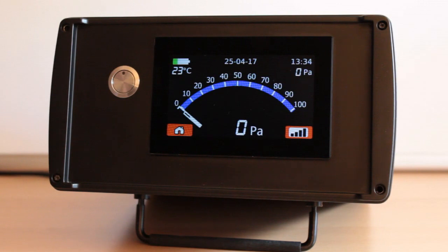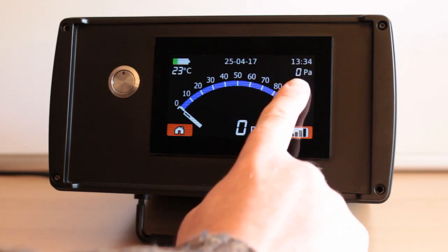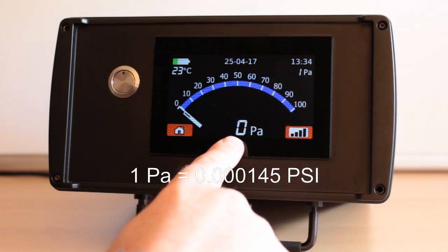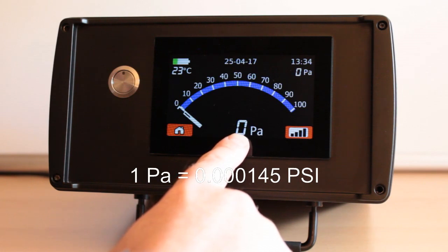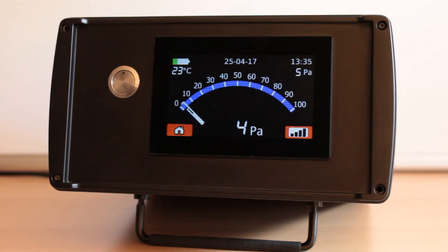Right, so I've got my pressure source plugged in, and it's running at absolute flat bus minimum. What you might notice is that this will flicker around somewhat because this is a live readout, whereas this is damped down somewhat. It is an average over the last 4 seconds, so it's a little bit easier to read. But if I start to turn the pressure up here, it should be about 10 pascals or thereabouts.